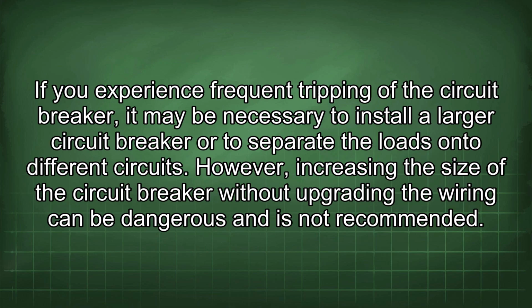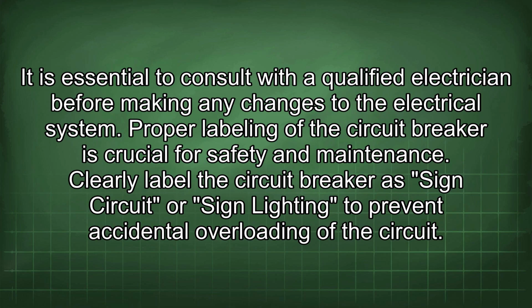If you experience frequent tripping of the circuit breaker, it may be necessary to install a larger circuit breaker or to separate the loads onto different circuits. However, increasing the size of the circuit breaker without upgrading the wiring can be dangerous and is not recommended. It is essential to consult with a qualified electrician before making any changes to the electrical system.